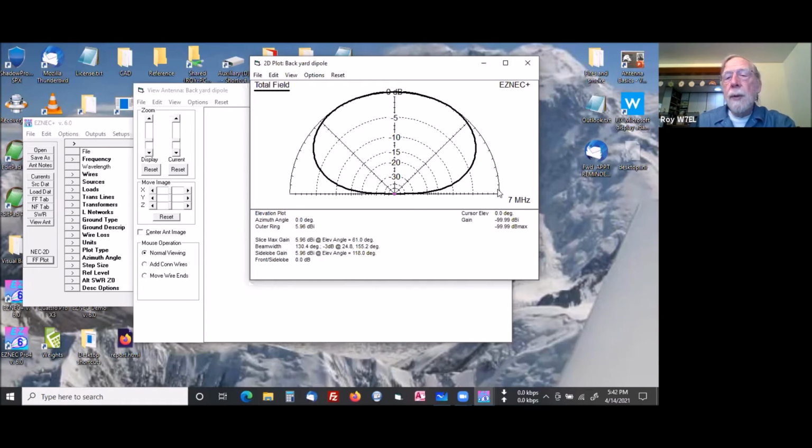And then the person goes up vertically, staying the same distance away from the antenna. The person goes up a bit vertically, goes up to say 5 degrees and measures it again, and they measure minus 0.937 dBi. And they go up and they continue going around, up and overhead, and then back behind the antenna, so that they're doing this whole loop, but staying the same distance away from the antenna the whole time, and measuring the field strength.